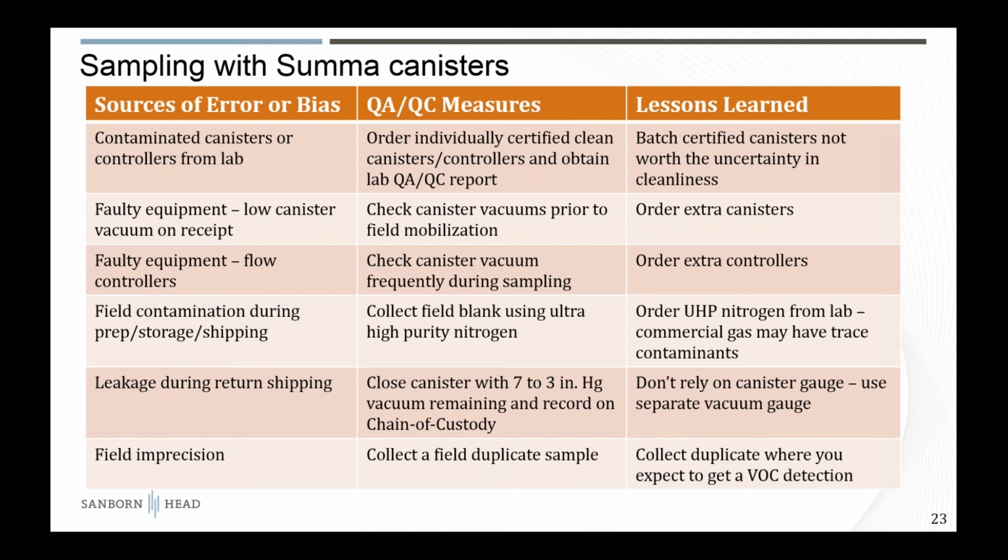And maybe one last thing here. You want to make sure, this is common practice, to close off your canister with some residual vacuum in it, record that vacuum on the chain of custody, and then the lab can compare that when they receive it, so you make sure there hasn't been any leakage during shipment back to the laboratory. And that would be another source of potential bias.